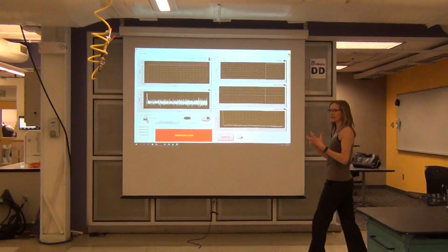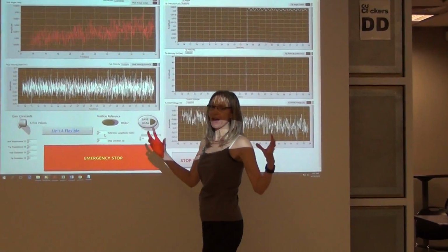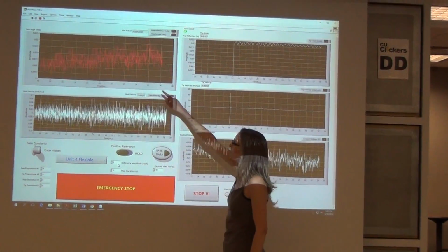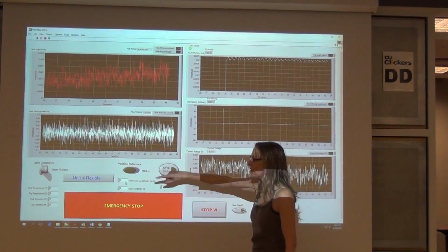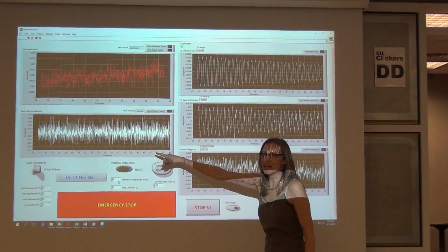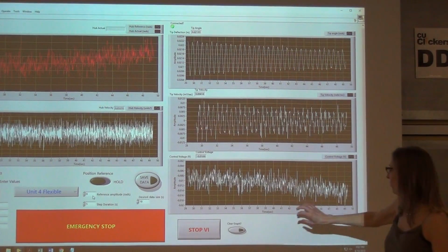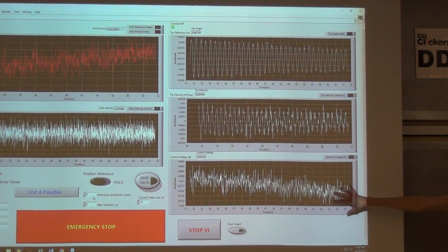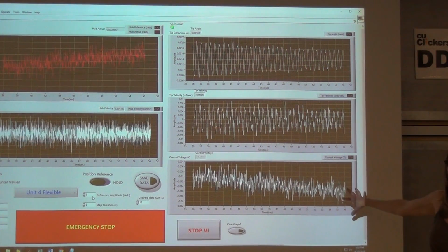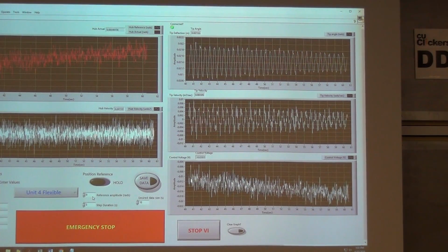All of these gains together, K1 through K4, all add up against their errors. So K1 times the error of position, K2 times the error in tip deflection, K3 derivative, K4 derivative. All of those add up to one motor voltage that's sent to the DC motor. So that control voltage will still be applied to and shown to you, and you have to make sure that that doesn't exceed 5 volts.